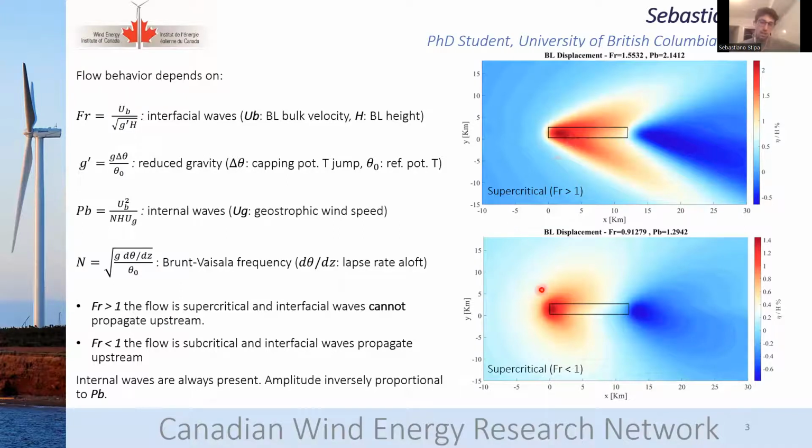And what happens is that a horizontal pressure gradient inside the boundary layer can actually change the behavior of the flow inside the boundary layer. For example, by slowing down the velocity of the flow particles which approach the wind farm. As a consequence, the wind turbines would see a lower free stream wind speed than expected.